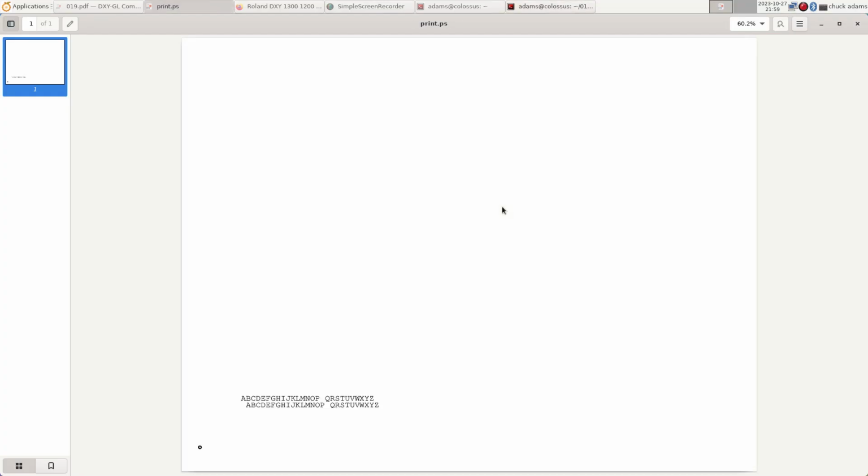And so we can see that, yes, indeed, this bottom line was done with a blank between the P command and the first letter. The second one is no space, so there is a space there. For the other commands, it doesn't matter, but for this one, it does. So we learned something. It's not in the manual. Also, that's the default font.